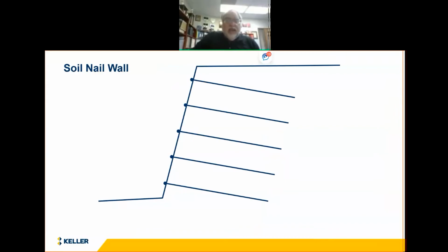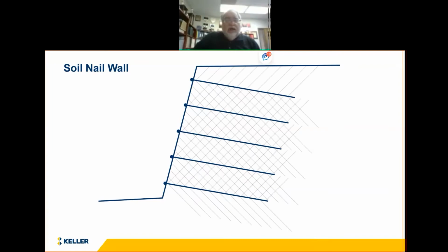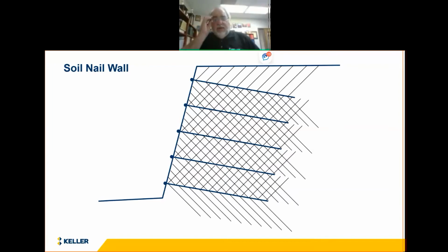To understand the concept of soil nailing and as it's done in a top-down manner, number one, and number two is how does it work? This is a little illustration we put together. So these are theoretical Rankine failure planes that are on phi minus 45 over 2 and phi plus 45 over 2. And so they intersect, and all these failure planes are possible in a soil nail application. So you can see here that the nails cross across, they're drilled and grouted right across all of those failure planes, and they support the soil across those failure planes, which is really great, as you can see here.